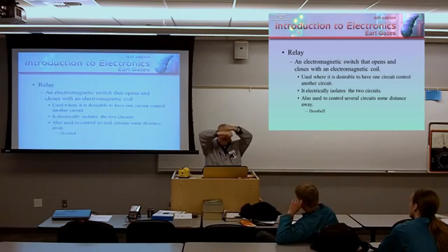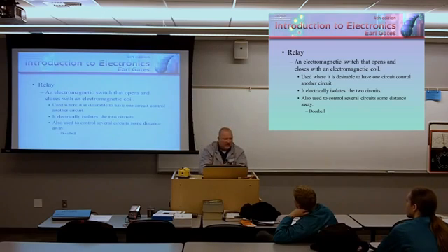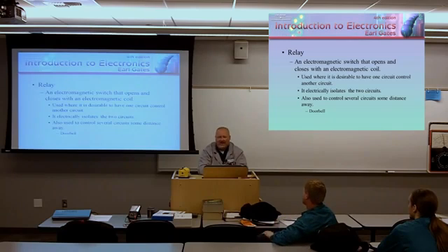Or I could do it the opposite way. I could be making electrical contact, and when I energize the electrical circuit, it's going to open the circuit. Relays also could have multiple ganged contacts, so when I energize it, I'm opening and closing a bunch of contacts. But a relay is an electromechanical switch. It's using electromagnetism to move that armature up and down.